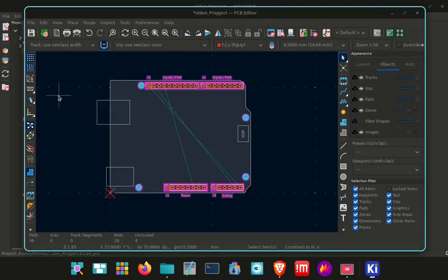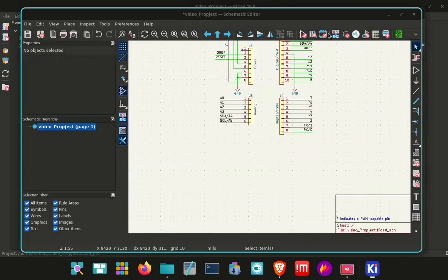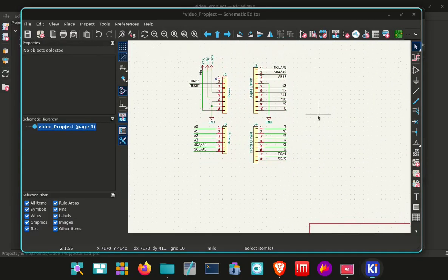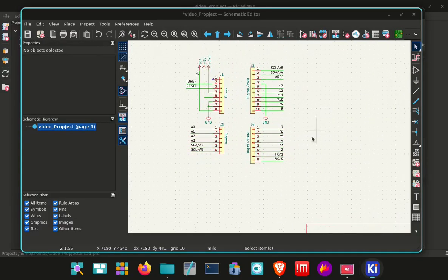Okay, wiring up our LED. This is our Hello World sketch of the physical world and electronics to make sure our board is actually working. So we want to connect up an LED, so we go back to schematic because we need to add it to our project first. Now we want it to come out of pin 6 and we want it to go round to ground. So in the circuit we are going to need an LED and a resistor.